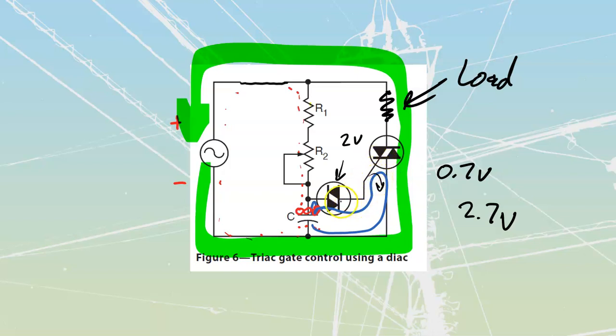This is going to shut off here because we're going to lose those electrons, right? Those electrons and holes are going to fill. So this little bit of current over here is going to shut off at that point, and then it's going to start to rebuild. And so while this thing is going through the first positive alternation like this, we might have multiple little builds and discharges off here. Build, discharge, build, discharge, build, discharge. But really it's just where the first build discharge is that is going to trigger. I'm just going to draw that little build discharge here in the positive direction underneath here.